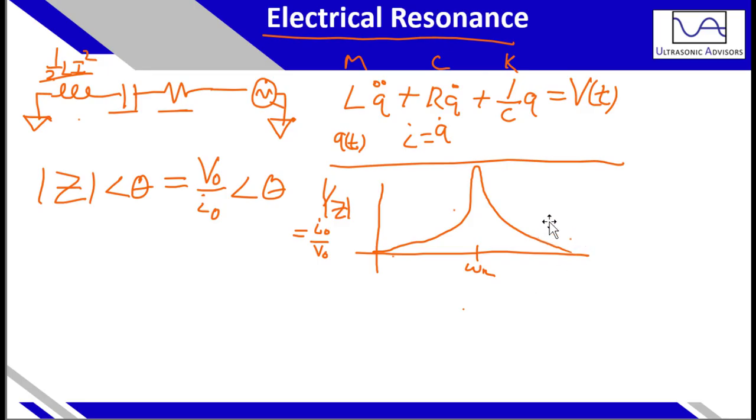At high frequencies, you are bounded or governed by the inductor. So as you increase frequency, the energy stored or the opposition to flow of current increases. Therefore, you have low current, or not low velocity, you'd have low current here at high frequencies. And also at low frequency, you have your capacitor dominating your circuit, which starts to behave like an open circuit condition at very, very low frequencies.